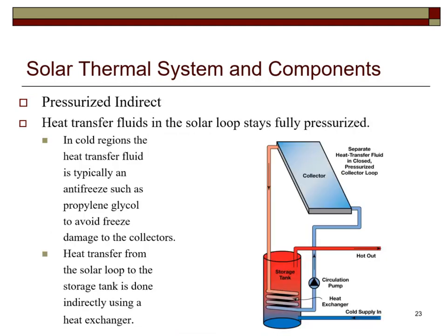The pressurized indirect is demonstrated. The fluid that goes to the collector is different than the hot water to be used. This allows for antifreeze in the fluid going to the collector. The indirect system is evidenced by the heat exchanger in the storage tank.